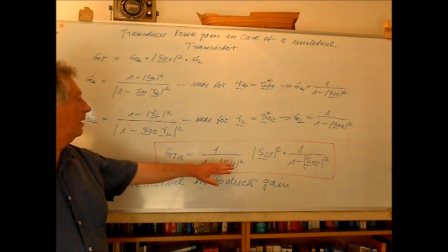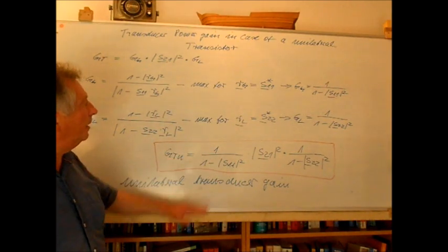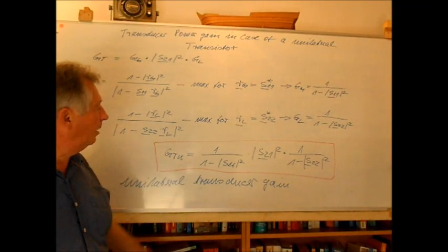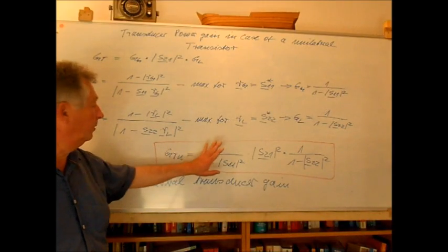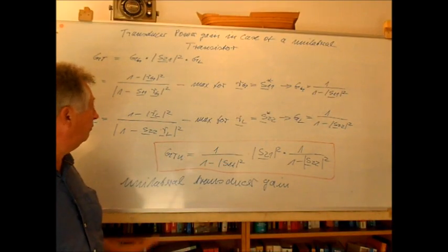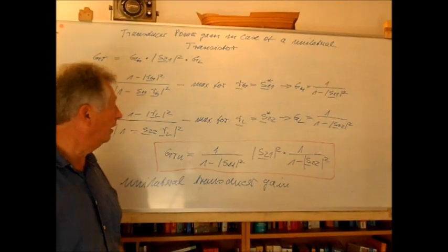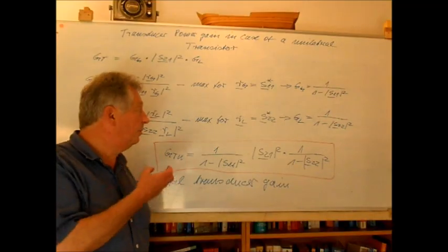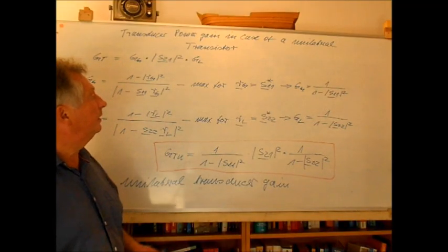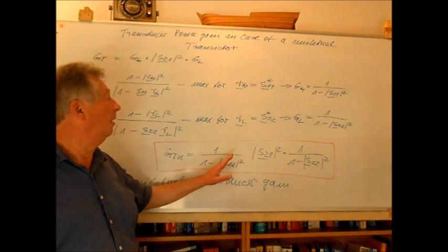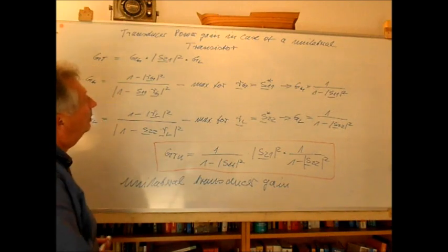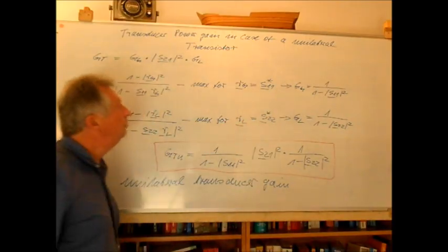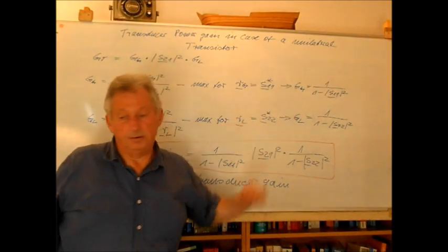So it is like this, that for a real transistor I can always assume that S12 is 0, and then I can in principle at least calculate the unilateral transducer gain, which would be possible with this transistor. Of course, this gives you an idea of the overall gain which is possible, but the problem is that for a real transistor S12 is never 0. Nevertheless, I will discuss in the next step what, from a practical point of view, this optimization means.